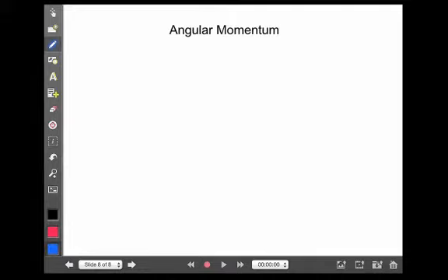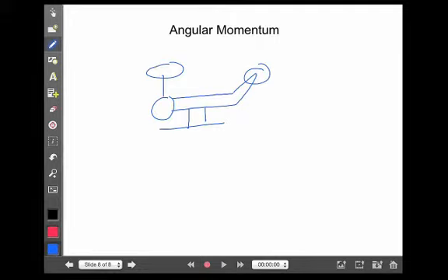If you ever look at the design of a helicopter, this can be a beautiful helicopter right now. The helicopter has two rotating blades. It has the large one that does most of the work of lifting it, and then it has this one on the tail. Well, the reason it has that tail rotor is because of conservation of angular momentum. You see, as the big blades start to rotate while it's sitting on the ground, the ground applies a counter torque to prevent the helicopter from moving.